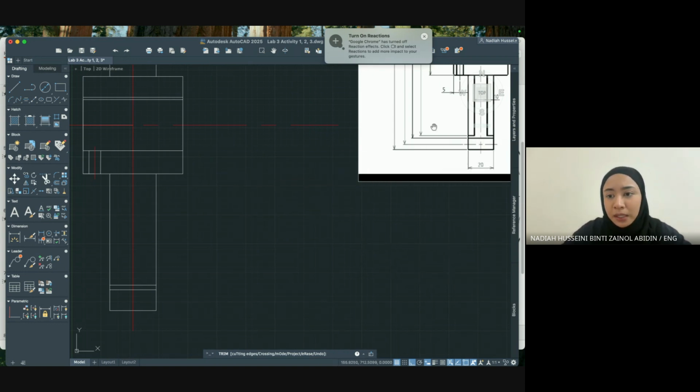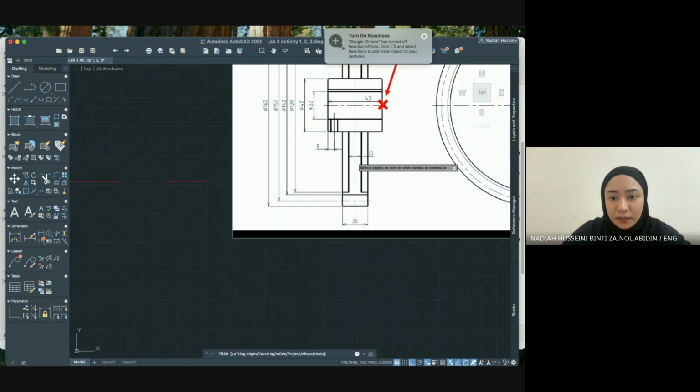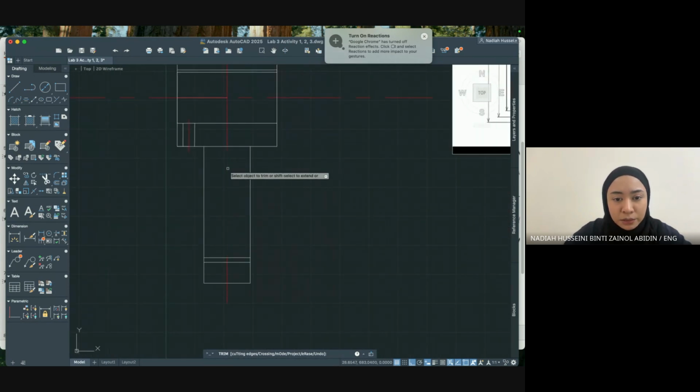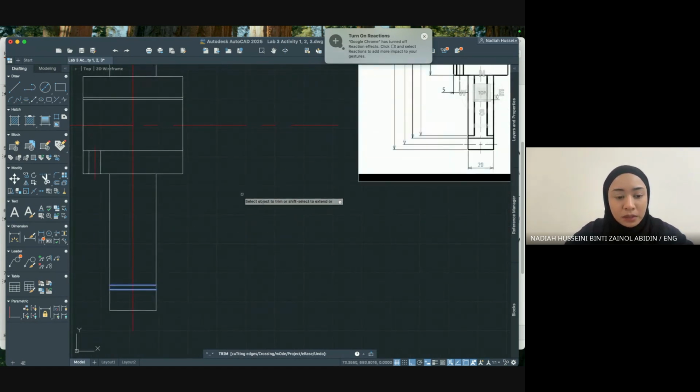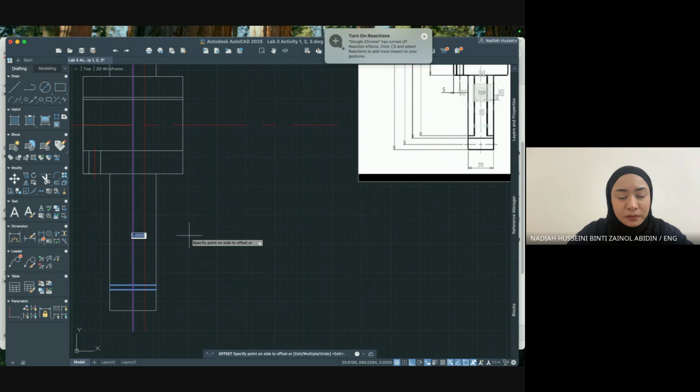Now we need to make this pillar looking thing. And this pillar looking thing from the midpoint is 5 on each side. So we can use the center line to do that. I'm going to click on that. Offset. Distance is 5 to the right, and again offset the center line to the left by 5.